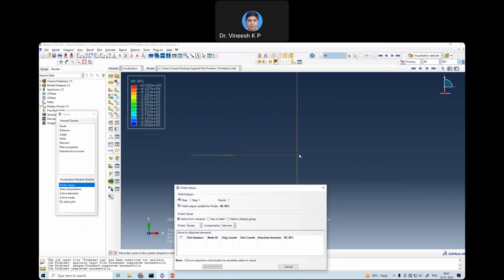You have to look at the support. Support, I think we did not define. We can just look at here. So reaction force here, you can see the support reaction force is around 100 kilonewton. And from here on node number 1, you can see it's around 500 kilonewton. So 500 kilonewton in the negative direction, which indicates that it is actually acting in the negative x-axis. 499,998, so it's around 500 kilonewton.